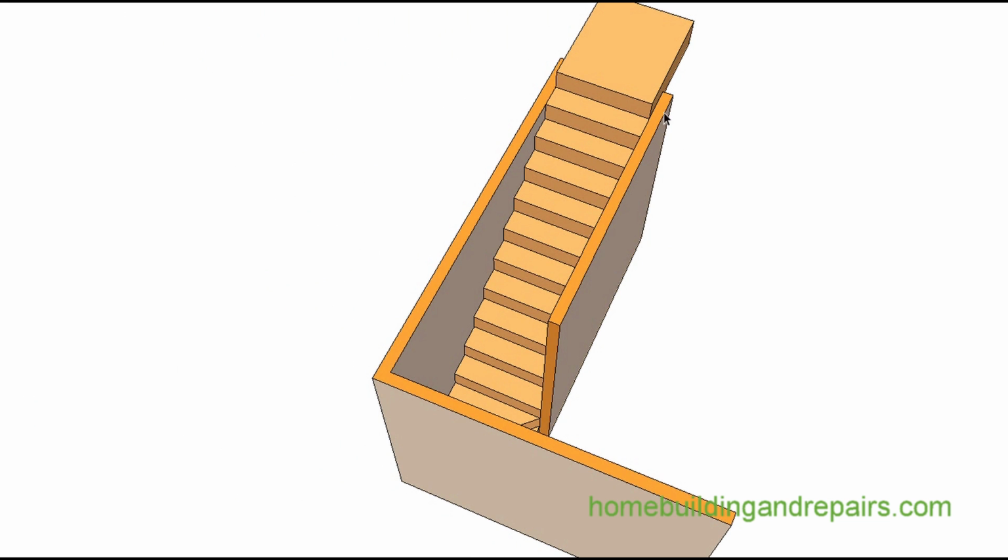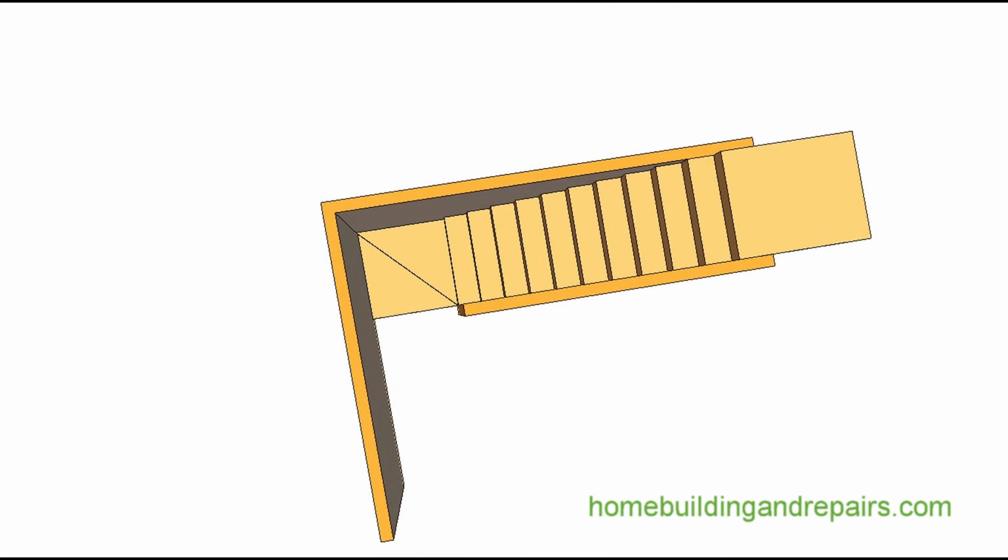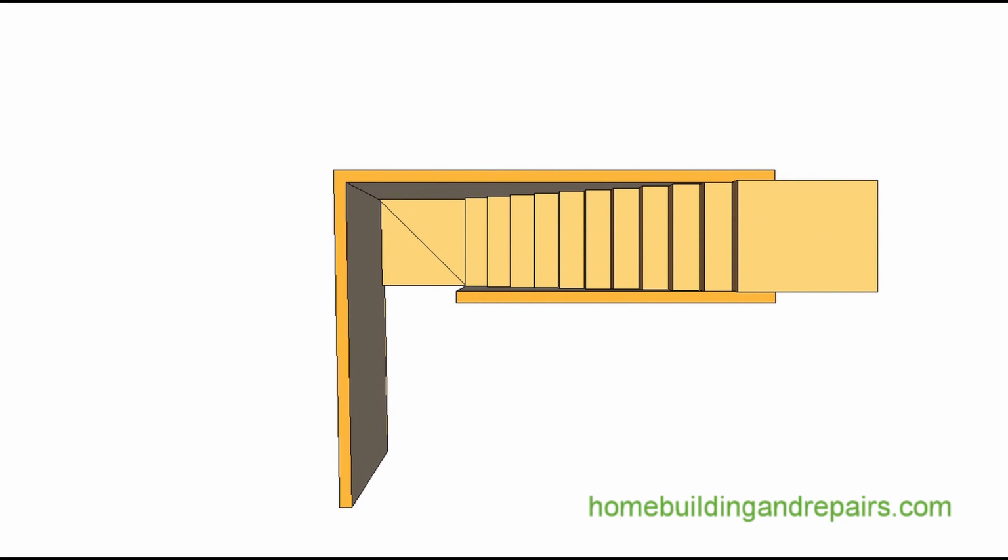So this is actually a question someone sent in. They wanted to know how they could redesign this type of stairway. They had 9-inch wide treads and 8-inch tall risers, which was the maximum distance on a riser. The minimum distance on a tread was 9 inches when I was installing stairs back in the late 1970s and the early 80s. So this is a common stairway we're looking at right here, but it's not always going to be the safest. And the people that asked the question actually realize this and would like to redesign the stairway. So that's why I'm making the video.